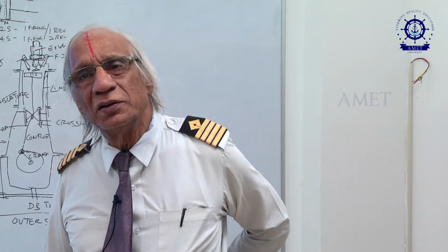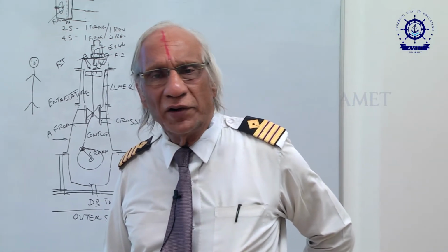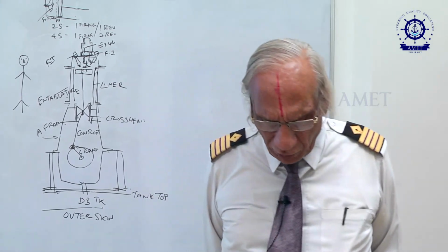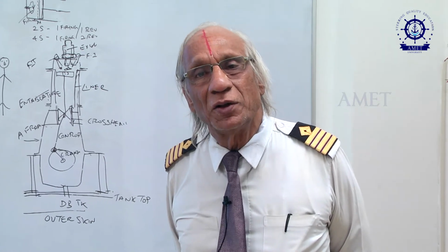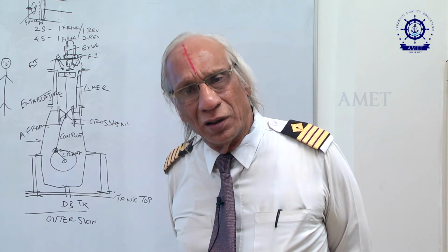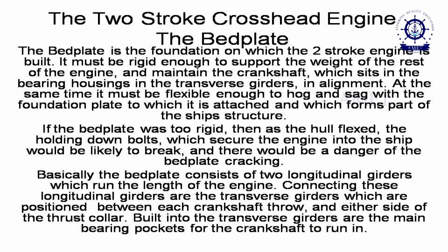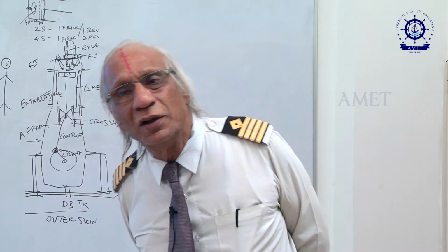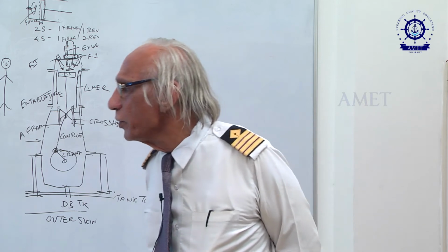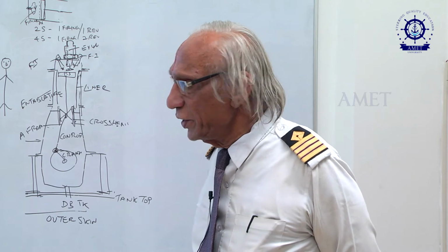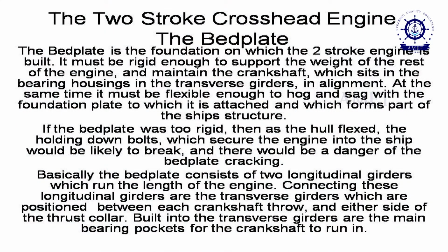It should not be too rigid. It should have some amount of flexibility. Why do you need some flexibility? Because the ship is moving in the water. You don't expect the water to be very steady. Depending on the sea condition, you may have a trough and a crest. So accordingly, if the bed plate sits on a crest or a trough, it is subjected to a bending moment. So the bed plate structure should have some amount of flexibility. At the same time, we should also have some rigidity to withstand the gas forces of the piston